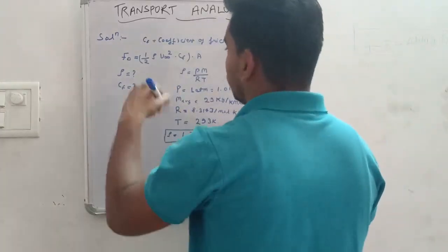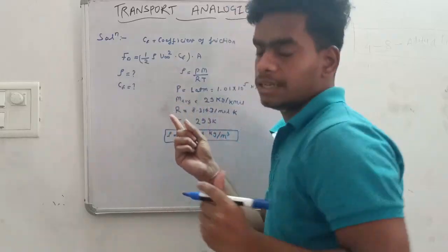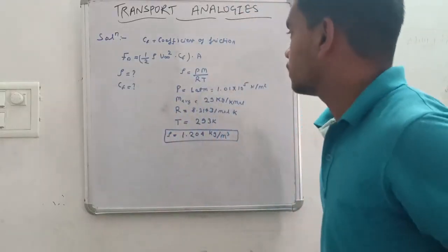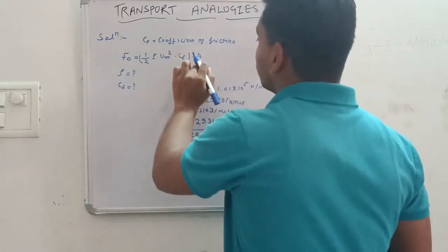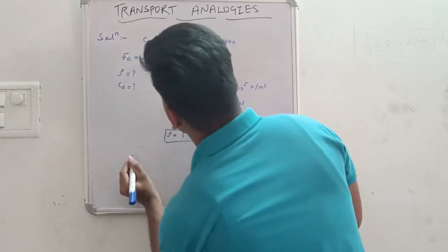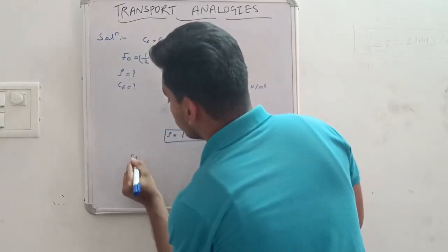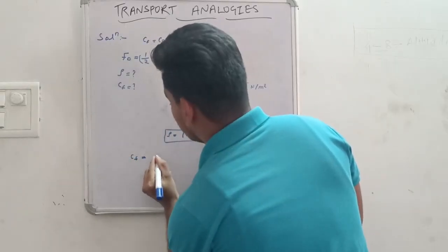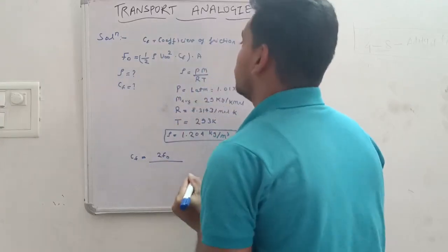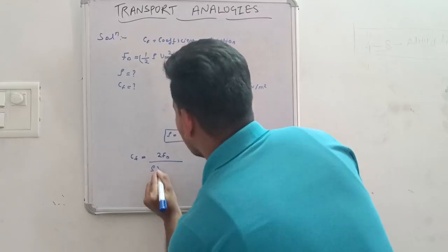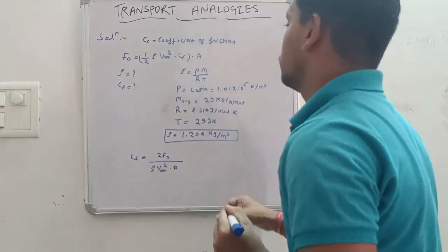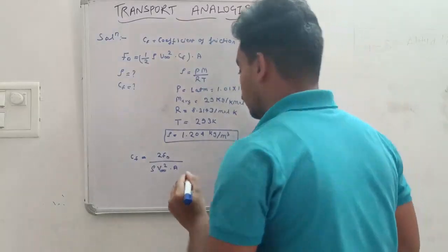So here by putting the value of U infinity, we know the U infinity as 40 meter per second. Yes, it is 40 meter per second. It is air velocity, and we know the area, we know the FD and rho. So directly from here we can calculate the value of CF by rearranging all the terms, CF = 2 FD divided by rho U infinity square into A.